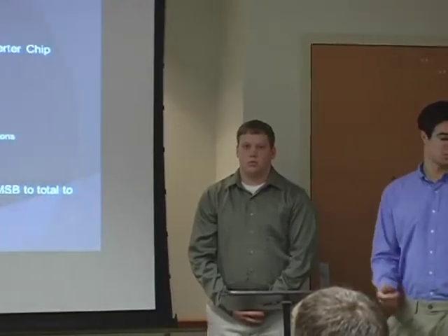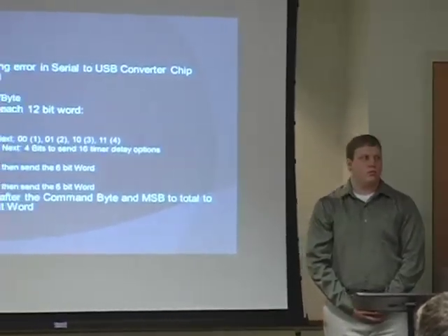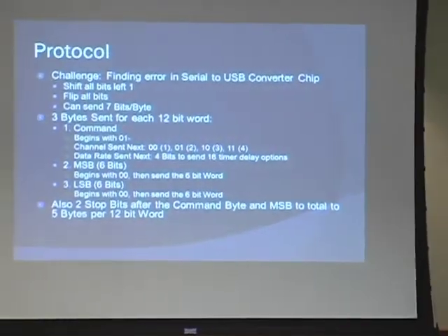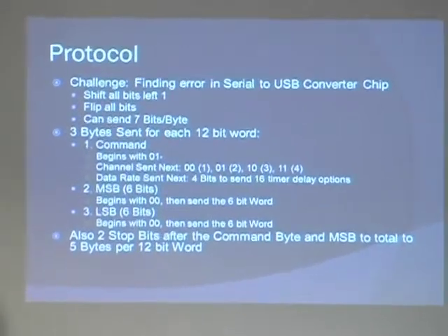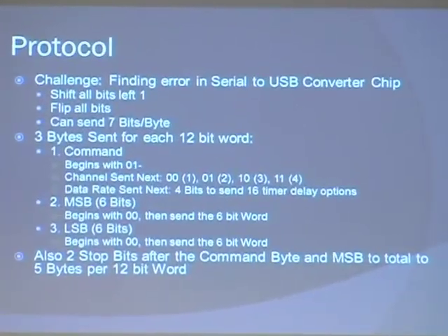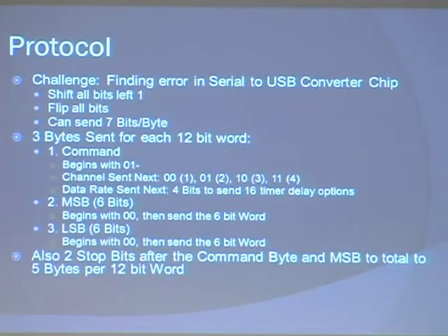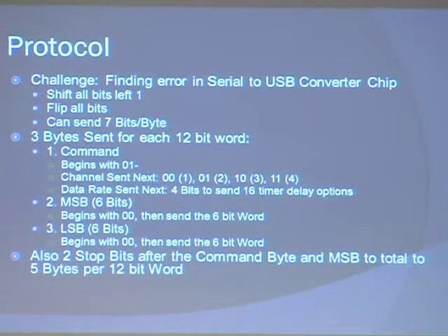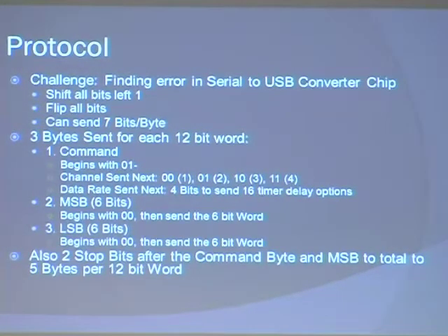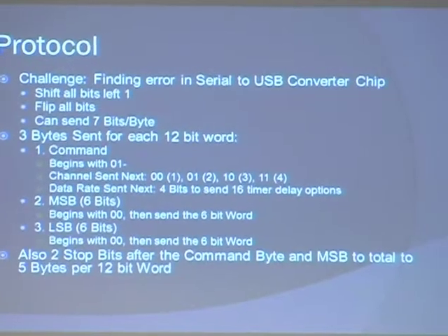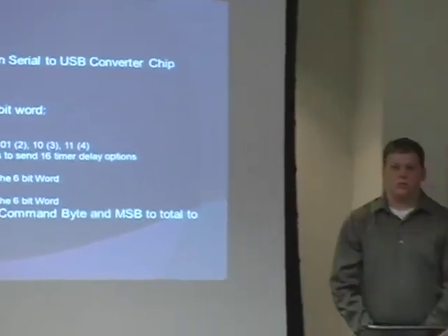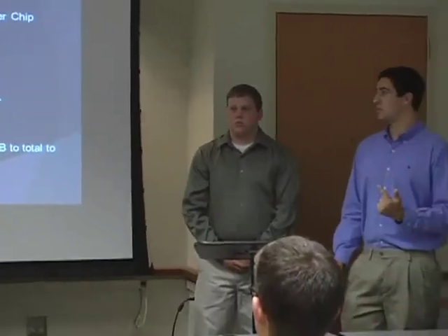We used a protocol for me to send data and Matt to understand, because we were sending 12-bit data points. The challenge was with the USB to serial converter. I had to shift all the bits left 1, I had to flip all the bits, and when I did this I was only able to send 7 bits per byte, so there were a few problems with that. But we didn't really have to change anything with our expected protocol, which was good. For each 12-bit word, I had to send 3 bytes.